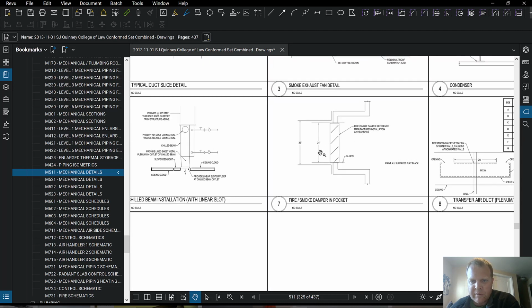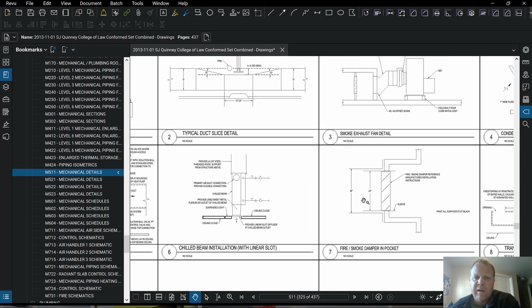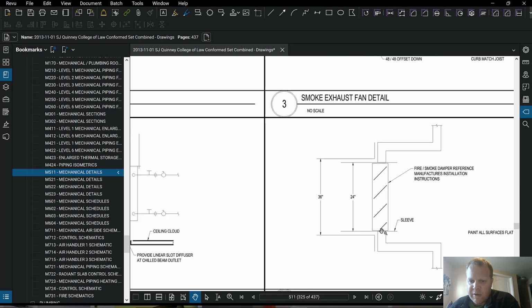Fire smoke damper. Anyway, the idea is that it'll just close off that duct, okay? It's just really showing turning vanes is all. It's like these dampers that are individually, they're all open like this, and then they're going to turn and shut like that, right? So there's a whole bunch of them in a row. These dampers, as they rotate, make it so no air can go this way. Hopefully that made sense.